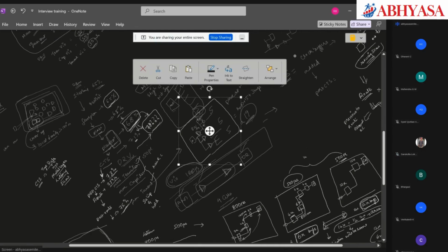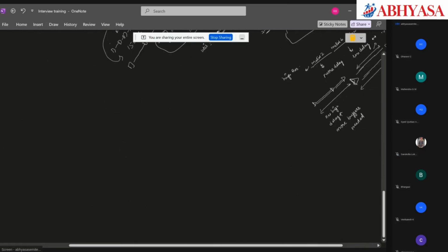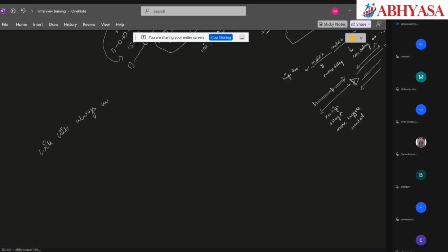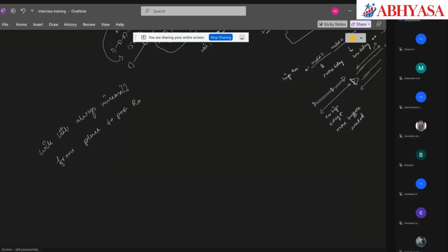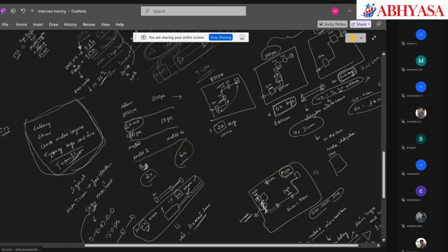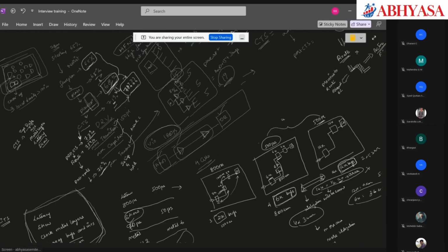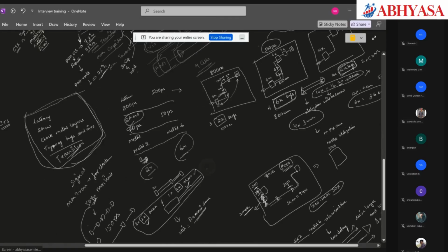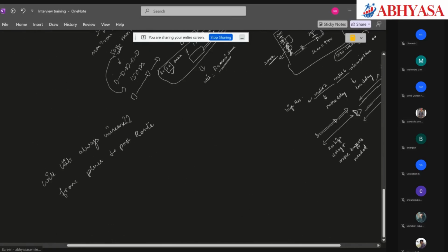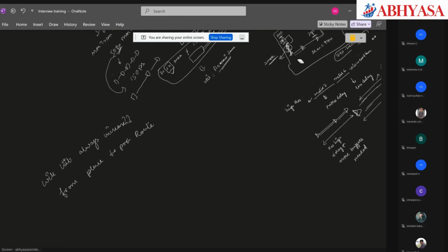Now, will utilization always increase from place to post route? The answer is no, right? Usually we see utilization increase. In the interview, you can say I started with 65, then 68 at place opt, CTS 71, 73, 75, right? And the interviewer will be happy. You might sometimes see the utilization also dropping. Let us say floor plan utilization is 65, place opt utilization is 63.